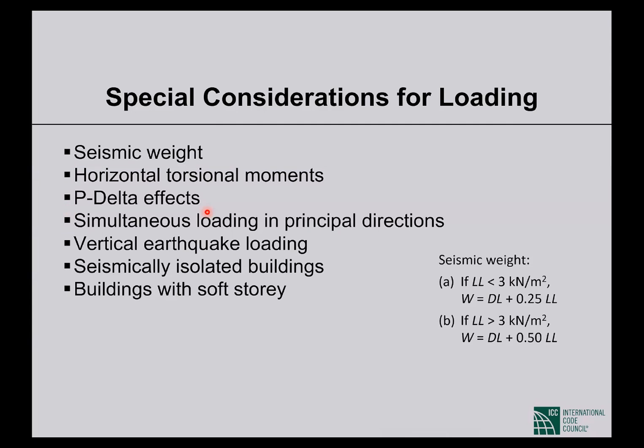So these things are very important that we all should be conversant with. Then P-delta effects: there is a factor or parameter called theta that we have to calculate to understand if we need to calculate P-delta effects or not. This is very important.